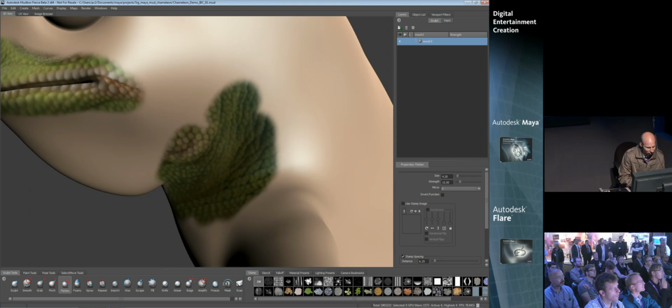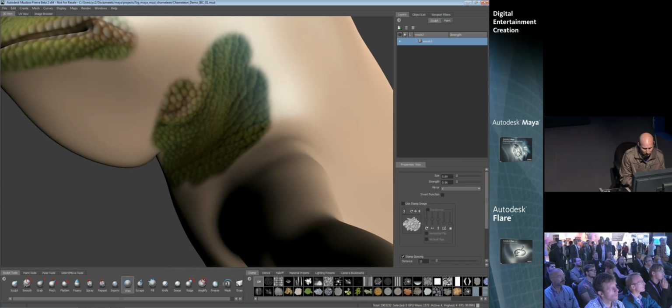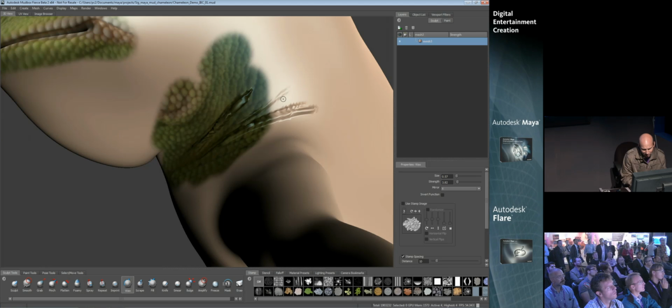So I'm going to switch from a sculpt brush. This time we're going to use a wax brush. So this one builds up a little bit differently. I'll decrease the size of that wax brush. Sort of go over here, and what I want to use a wax brush for is painting some folds and some creases. Let me decrease the size of that, and I'll overdrive this so it's really visible there. So we'll increase the magnitude of that and sort of paint out some cracks, some creases.